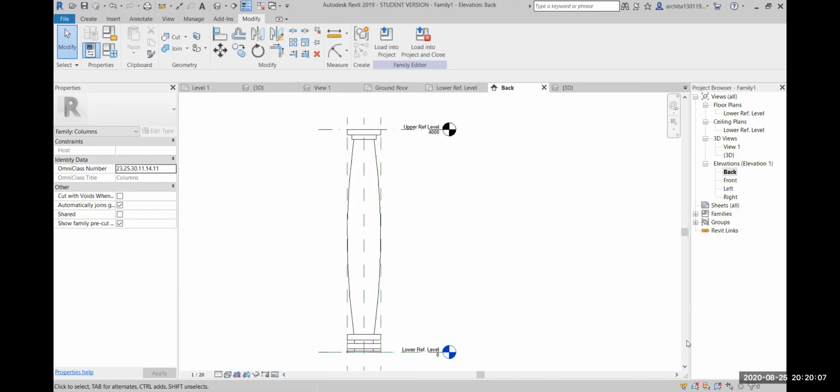Sectional, ma'am, that is the reference plane, no, ma'am? Yeah, on the reference plane only, because when you make several reference planes, and on each reference plane you create a profile, that means when you select all of them together and create a form out of it, you will get one proper single form, right? So that's what I'm referring to as sectional profile, what we create on each work plane. So not just an arc, it will be like a complete section of the table. At one point, whatever the section of the table is, it will be that. Okay, ma'am. I'll try that.